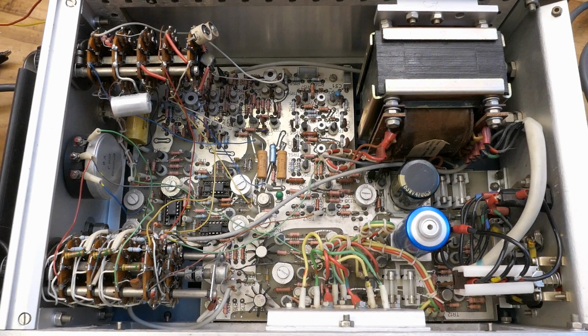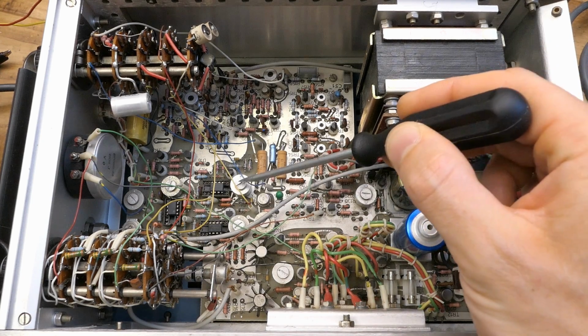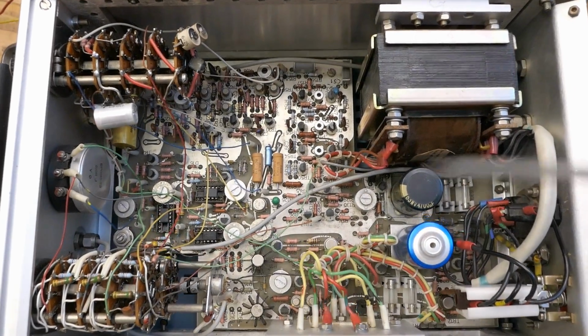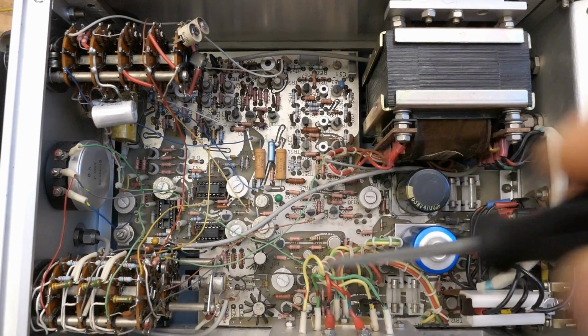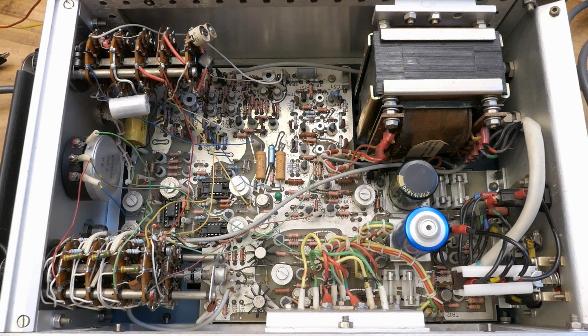Of course resistors are the least common thing to fail, especially the low power ones. It could be a poor contact in some of these adjustment potentiometers on the board or trim pots. There is a lot of them. There are some smaller ones also. But it could also be somebody just randomly turning the potentiometers in it. And this is like the worst you can do, just randomly turn everything without knowing what it does.